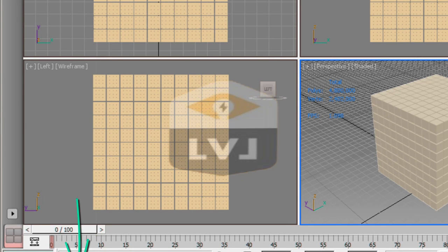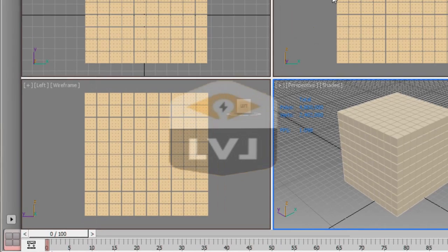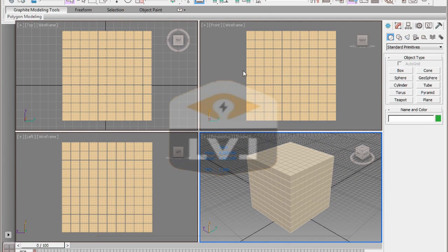Notice down at the bottom left side of the screen is my render time. Your time will be different depending on the computer system you're using. Faster systems will have shorter render times, where slower systems will have longer times. This is the amount of time it took to render this last frame. Remember your render time, or you can write it down. Render the perspective view again by clicking the render button on the right-hand side of the main toolbar.